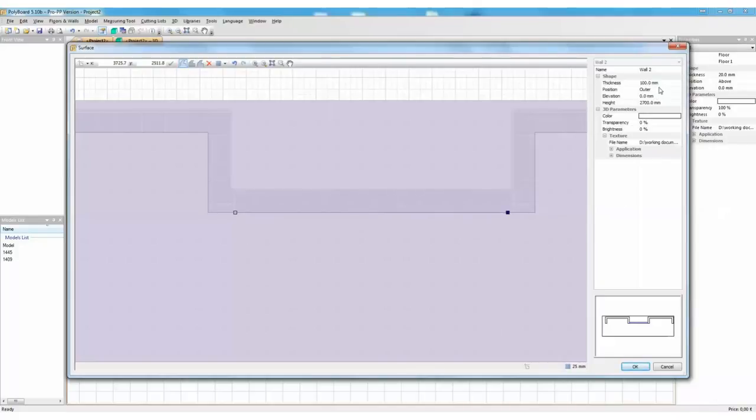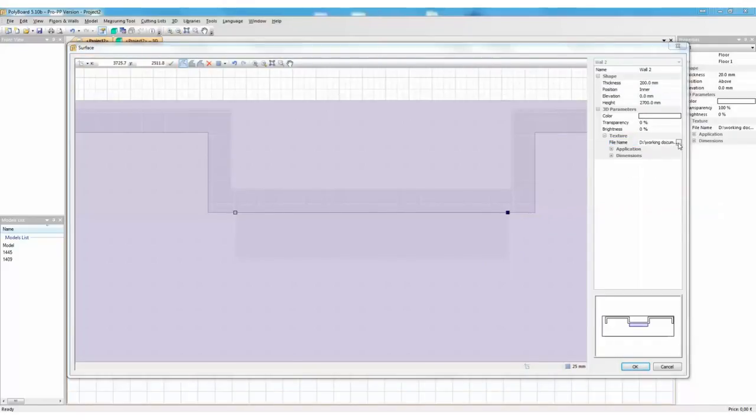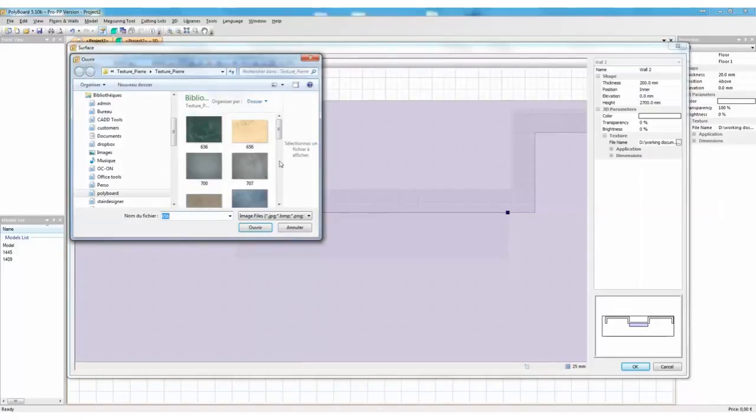The thickness of this wall, I'm going to give it something quite deep, something like 200 mil. I'm going to click it onto the inner side now, so the wall will be clipped this side here. It's 200 millimeters thick.